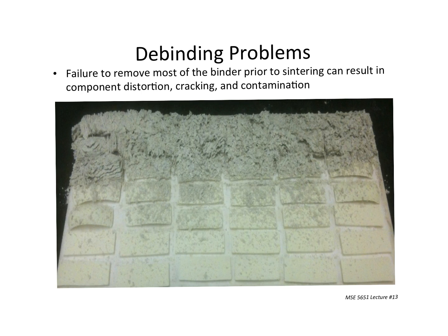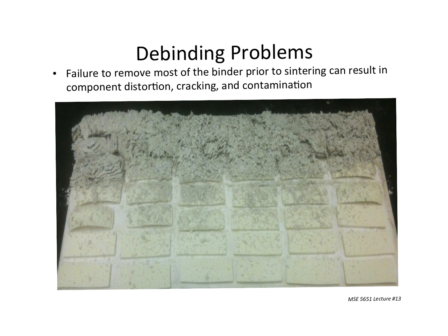This involved making, first off, nucleation and growth of nanoscaled zinc oxide, which you can do via a chemical process. We would fabricate this powder and then compact it into 4-point bend test bars, and then do a Weibull modulus determination on this. The lab had some issues, but what I'm showing you here is a series of specimens, and the difference between the top and the bottom portion.